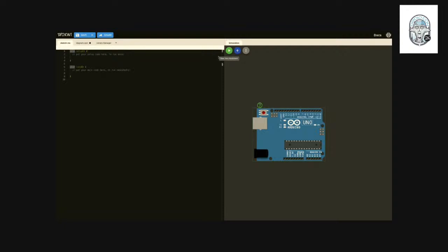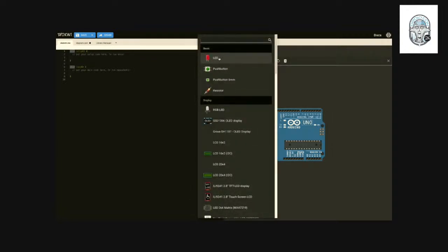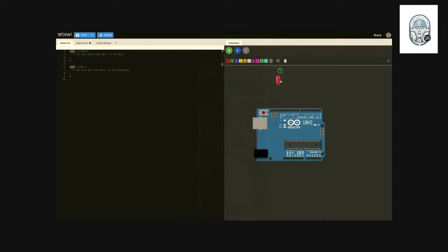So if you start the IDE and you're starting a new project, say we want to control an LED, a simple way to try that is in the simulator, because we can't blow anything up in here. We can add a new part here. Select an LED, for example. There are other options here later. Then we can simply connect it. You have the anode and the cathode, and you're going to have to connect ground.